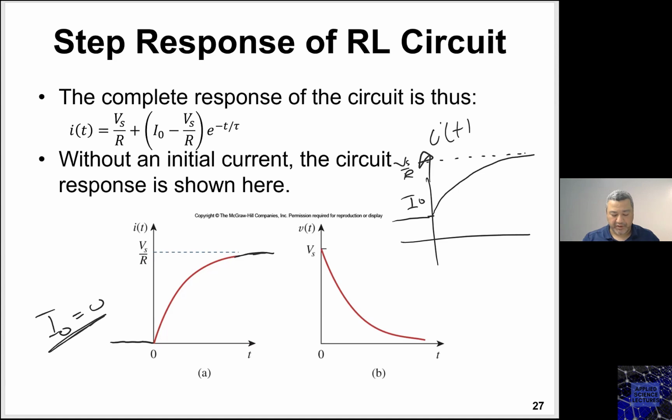So always keep in mind, if a capacitor is being discharged from initial voltage, it will discharge exponentially till it reaches zero. If a capacitor is being charged in a circuit that has no inductors, which means first order differential equations, this voltage is going to increase in the capacitor exponentially.